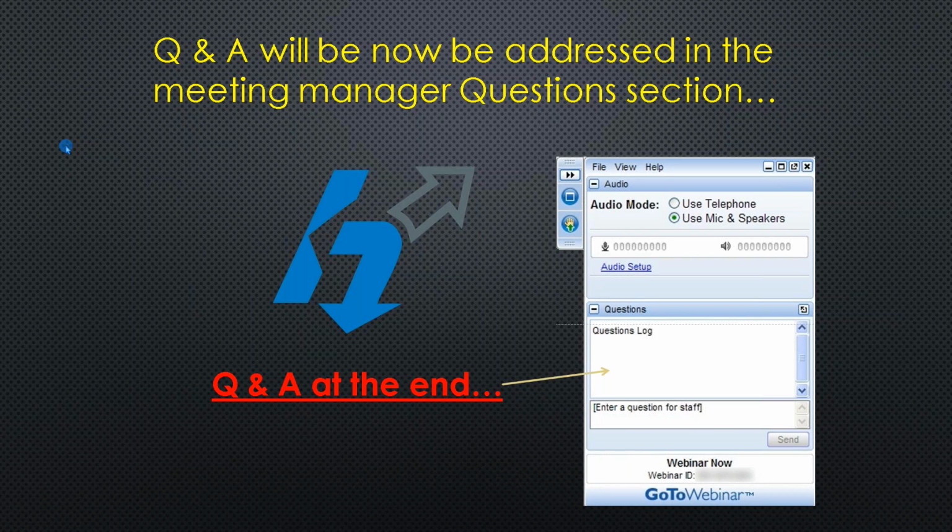All right. Is using the convergence settings with the H refinement the same as manually charting the convergence? No. The H refinement goes back to those individual tests that are happening as part of the one test. So the H refinement is happening behind the scenes.